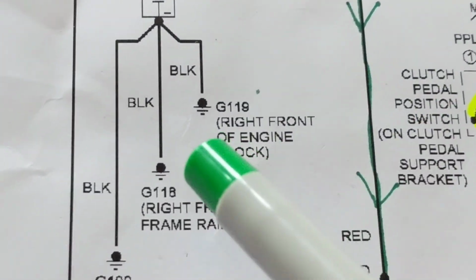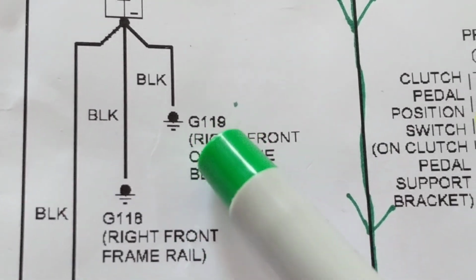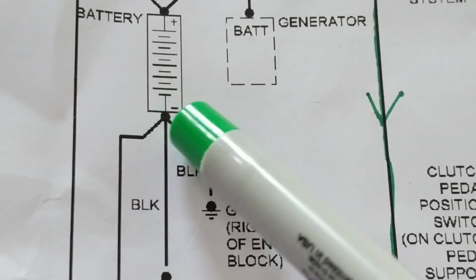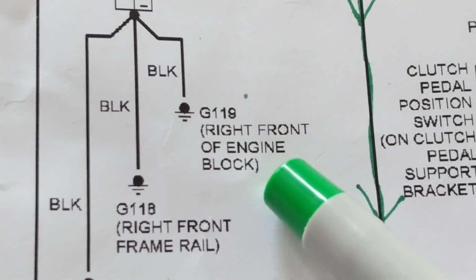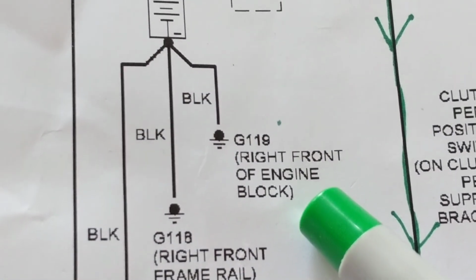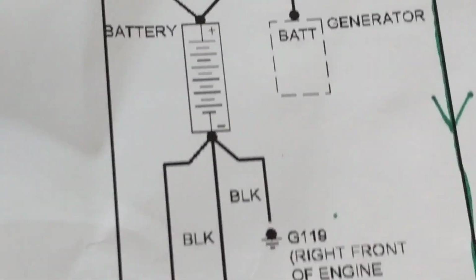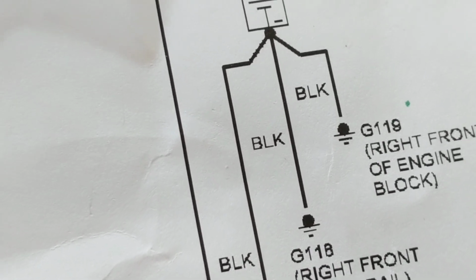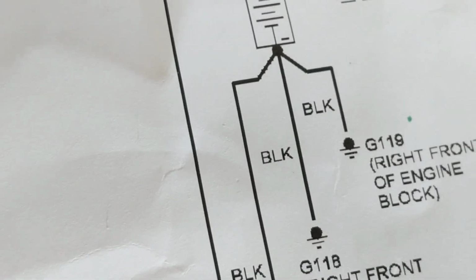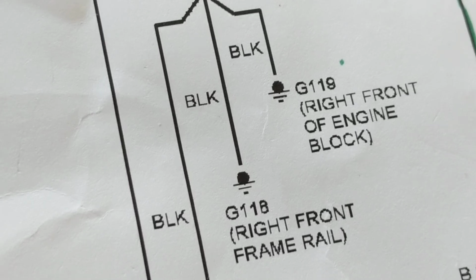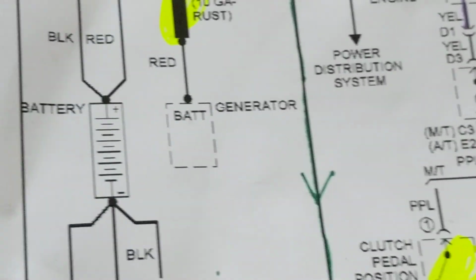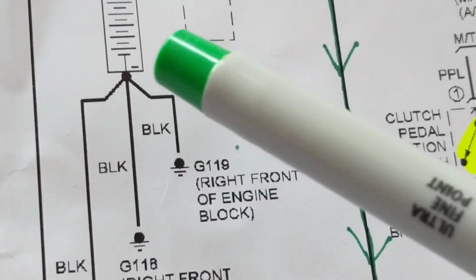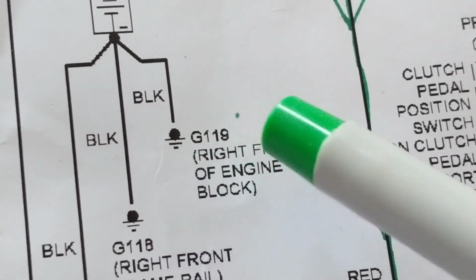I just showed you a ground. This is a physical ground. The other side, if you ever wonder where the negative goes, to the engine block, as I said numerous times. Sometimes if you have nothing coming on, not even the power doors work, not even the instrument cluster comes on with the dashes in the dashboard and the gauges, that means you have nothing coming on. That means sometimes you can have the ground not making a good connection to the engine block.